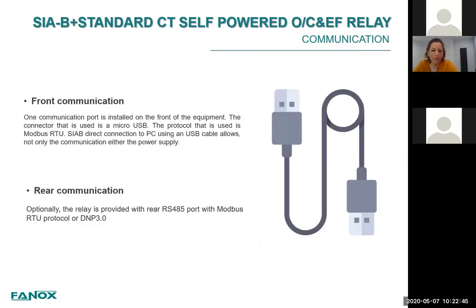And as in the previous relay, just to remark the importance of the communication, I remind you that we have the front communication port, micro USB, to communicate locally and also to switch the relay on directly with the laptop, and also the remote communication, the RS485 port, with a protocol selectable between Modbus RTU and DNP3.